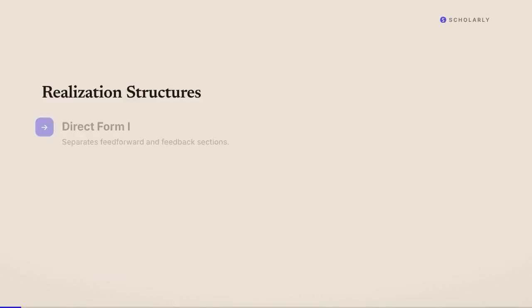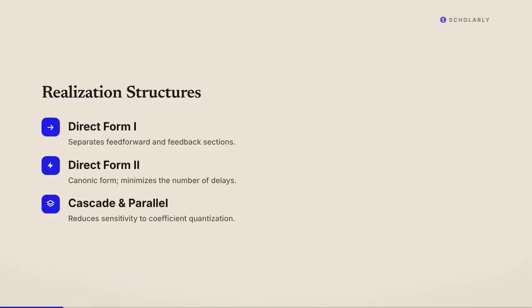In practice, IIR filters are implemented by carefully placing poles and zeros. A zero close to the unit circle creates a notch or attenuation at that frequency, while a pole creates a peak. To keep things stable and minimize noise from rounding errors, we often break high-order filters into second-order sections or biquads. This ensures that small errors in the coefficients don't lead to a total system failure.